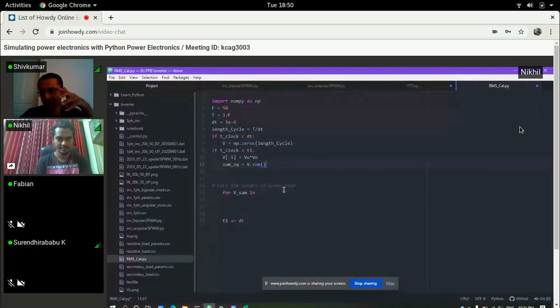The next step is you have to do the division, because first you have to do the division, and this division is the current RMS value. After you calculate the RMS value, before you get the next sample, you have to do shifting. So we have to divide it by number of samples. Exactly. So now this is your final RMS value. It can be a variable storage element, because you want to plot it, right? So it will be in this if loop itself. Yeah, it will be in the if loop itself.